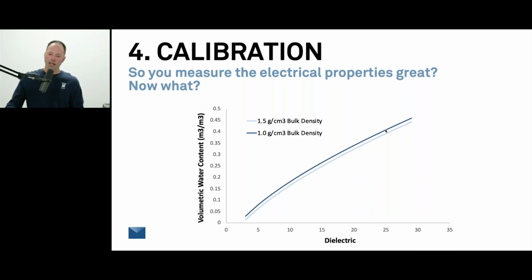And you'll get a factory calibration with almost every sensor. That's basically what your accuracy specs on the website are based off of. So when you're shopping from sensor to sensor and you see 2.5%, 2%, plus or minus 3% water content, there's almost always a caveat that it's calibration dependent. Volcanic soils might not fit a calibration very well. With high organic matter contents, you might need a different calibration.